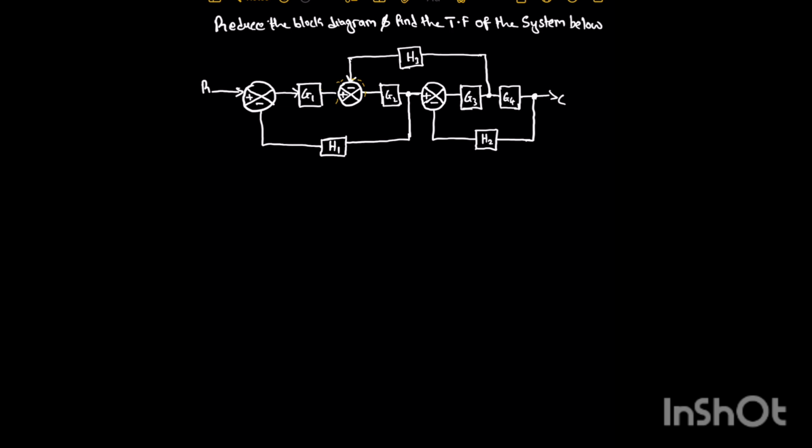First of all, though there are many rules, you mustn't use exactly the way I did in this one in particular. There can be another way out also. But to me, first of all, I would move this summing point to come before this block. That is the first rule I have applied.